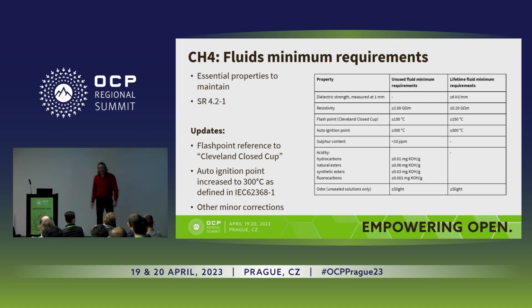Dielectric strength, 6 kilovolts per millimeter, should be the dielectric strength over the lifetime of a fluid. If you get below that, it's just not suitable for protecting electronics, right? So we want to make sure that any fluid just meets that. If you can't meet it, you shouldn't be an immersion fluid, right?